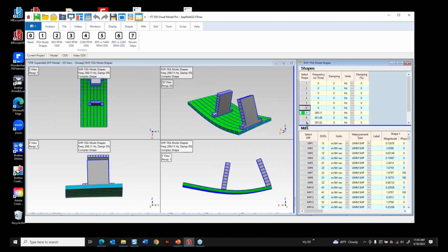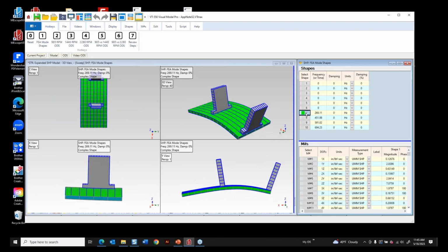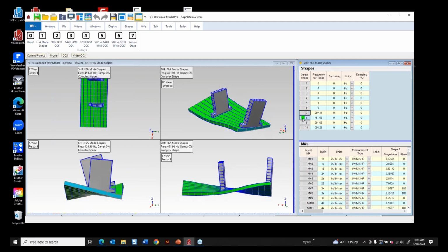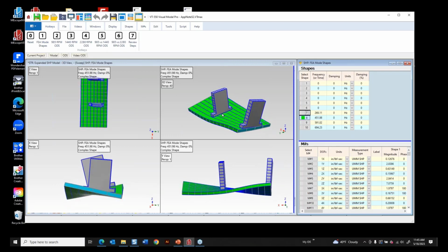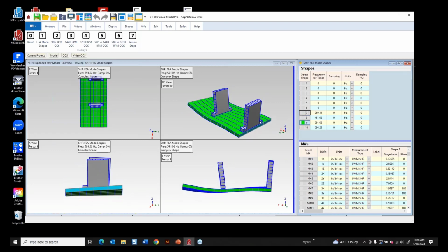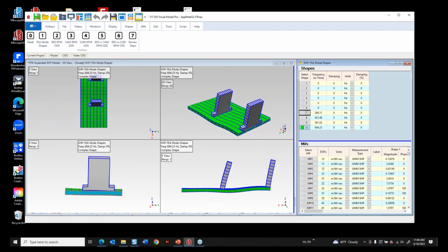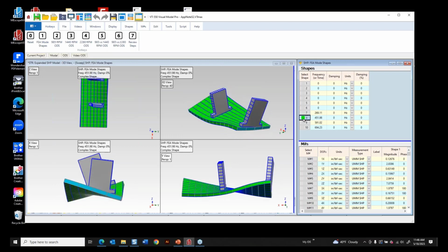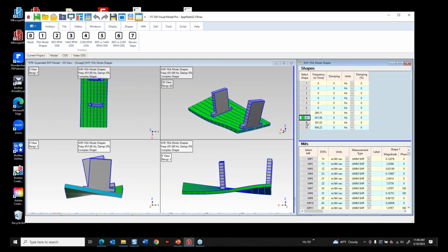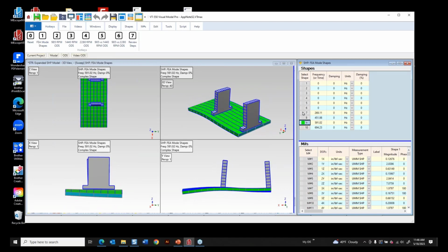Now this mode at 269 Hertz is, provided that I've built a good model with the right elastic properties and density of the aluminum material, there it is. And I've made a very stiff joint between the bearing blocks and the base plate, even though they are actually screwed on there, but we just assume that it's a very stiff joint there. And there are 4 flexible modes now. First bending, what we call first bending, and then first torsion.